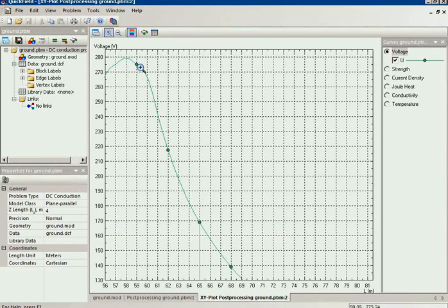Next step, the voltage drop is 5 volts. Next step, the voltage drop is 25 volts. So this is the dangerous area where there is the high step voltage drop. Next step, it's about 22 volts. Again about 20, and the next step is only 10 volts.